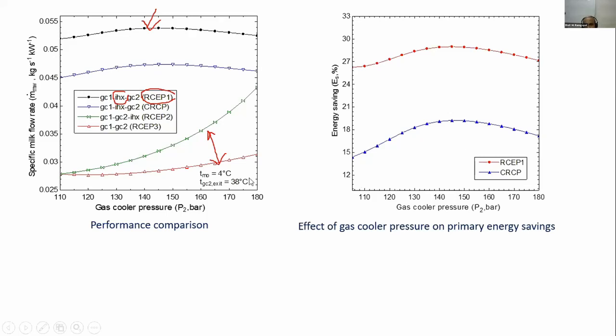then you can see that the energy savings with the transcritical CO2 system without ejector can be about 20% or so, and with ejector it can go up to around 30%. Okay, so you can get a 30% energy savings. This is substantial energy savings. Of course, the initial cost of the transcritical CO2 system may be higher than the combined cost of your boiler and R22 system, but considering the significant savings, the payback period may not be very high.